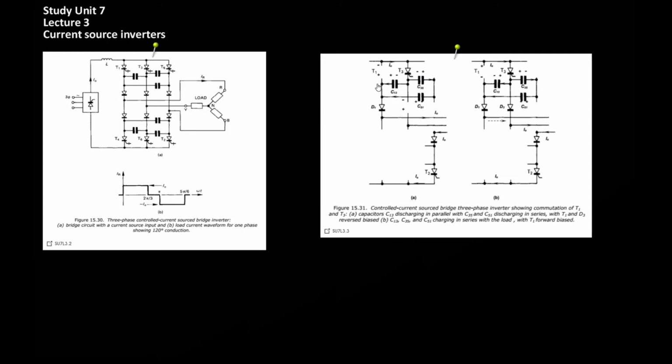So a typical application for a three-phase current source like this would be to feed and control a three-phase induction motor which has very high power requirements. This circuit can then be used to control the motor either by varying the amount of current which is provided by the current source, or by varying the voltage across this feed inductor, which will also regulate the current being supplied to the converter network.